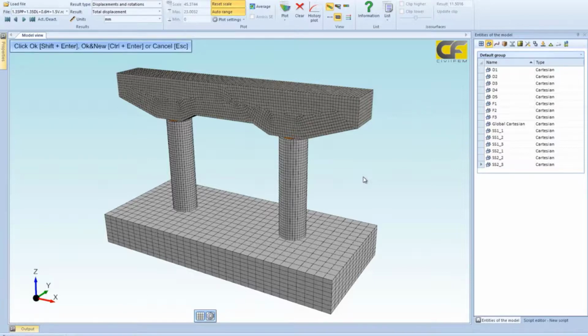With this new utility, CivilFEM will integrate the stresses of those sections, and we'll get forces and moments as results. Once we have those forces and moments, we can perform a code checking or design according to standards.